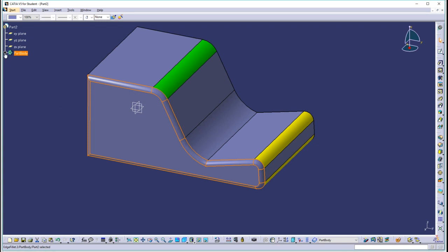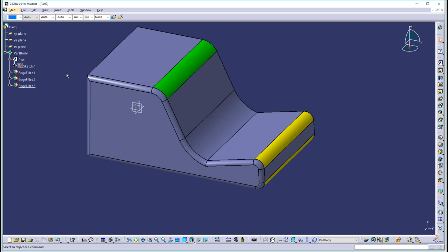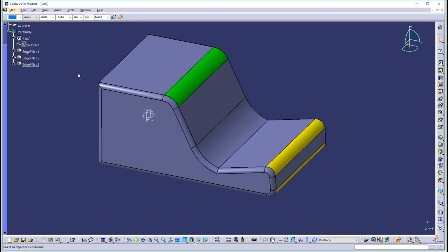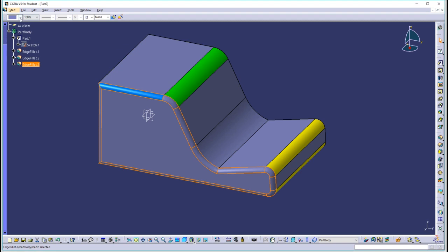Now let me show you the wrong way to color this. If I tap out, I'm pre-selected now, and normally I come up and color it. If I tap out and I go, oh, now I need to color that fillet, so I select my fillet and color it blue, well, it gets just that face. What you really needed to do was pre-select the whole fillet and change it to blue.